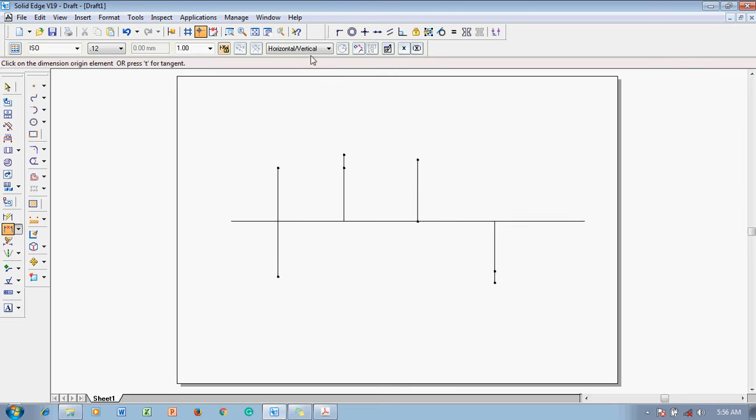Now in distance between, you can see this is the ribbon bar which is going to show you. By default it will be 1, let it be 1. This is a scale factor which you are not going to change. And now you can see this is called driving. The driving should always be on, that is nothing but the orange color indication must be there. If this orange is not there, then whatever you are going to draw will not be according to the requirements.